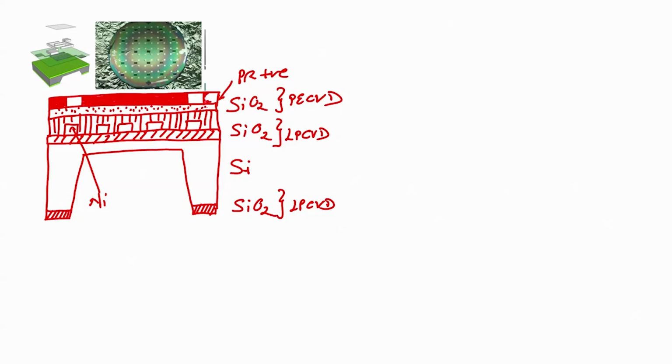right. So, what is this mask? This mask is a dark field mask. After loading the dark field mask, the next step would be to expose, right, expose the wafer with UV light.